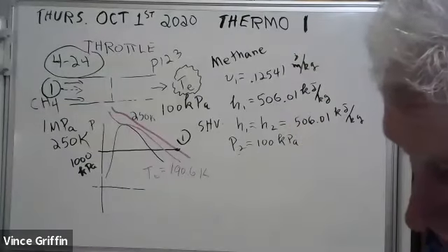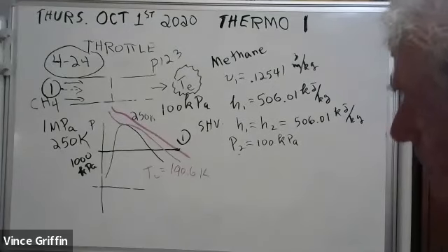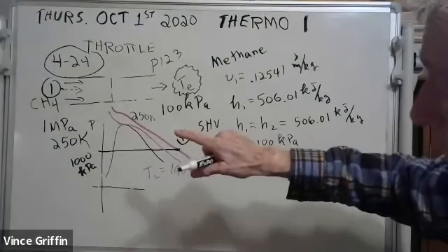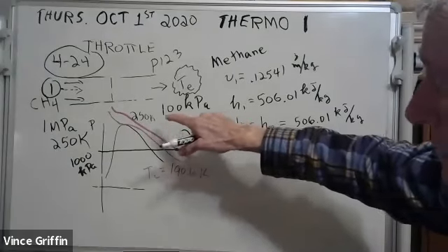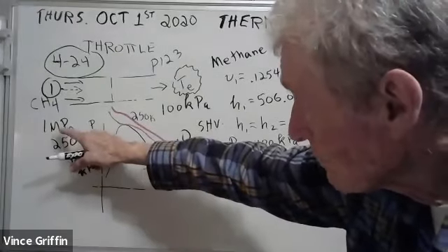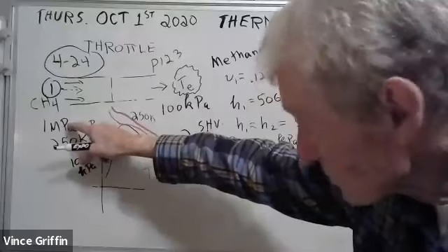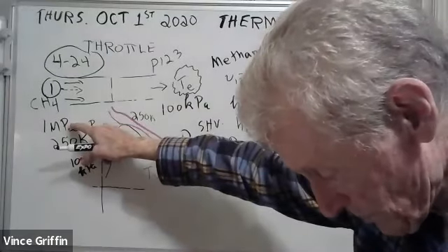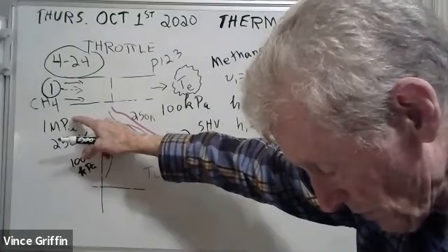Nathan, did you understand me? I do. So I'm looking at the superheated table now, and I'm looking at 250 degrees Kelvin and 100 kilopascal. Wait, 1,000. Nathan, you want to look up one megapascal, which is 1,000 kilopascals, in the superheated methane table.